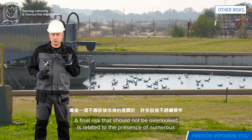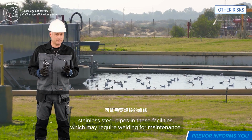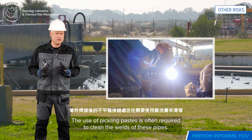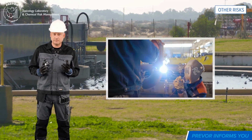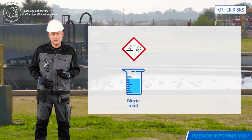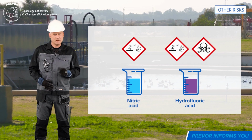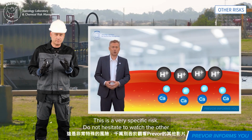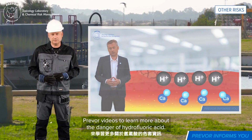A final risk that should not be overlooked is related to the presence of numerous stainless steel pipes in these facilities, which may require welding for maintenance. The use of pickling pastes is often required to clean the welds of these pipes. They are usually composed of nitric acid, a corrosive product, and hydrofluoric acid, a corrosive and toxic product. This is a very specific risk. Do not hesitate to watch the other Prevor videos to learn more about the danger of hydrofluoric acid.